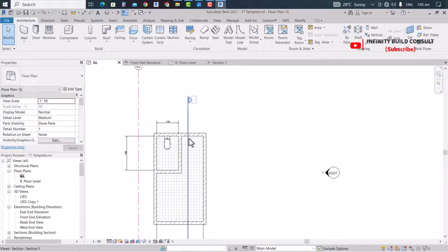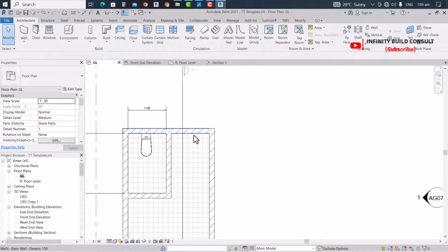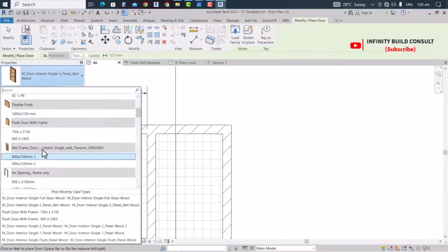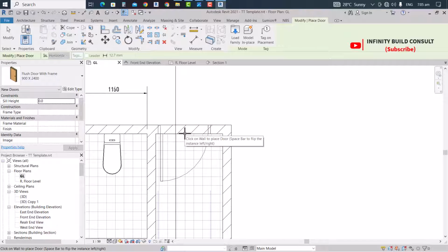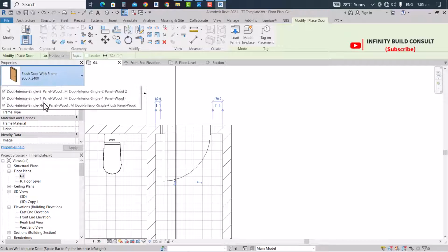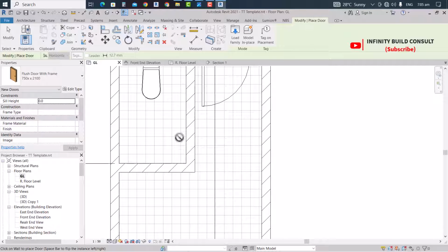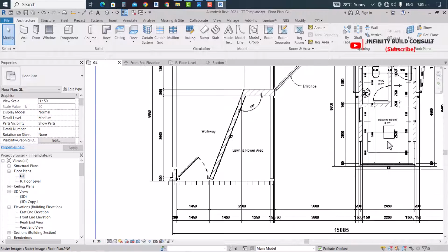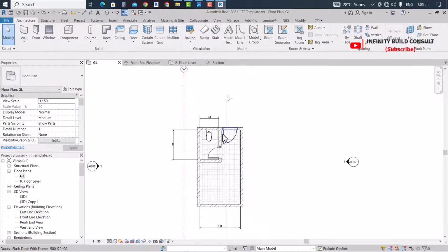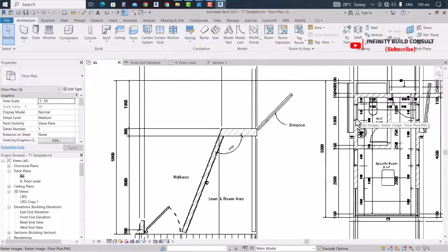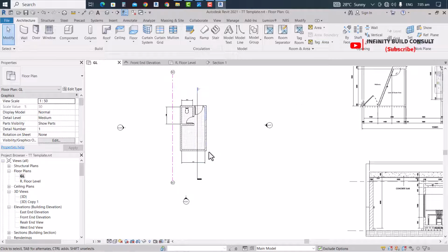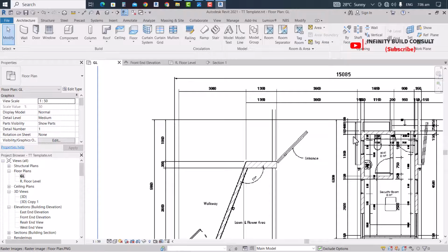Okay, the next thing that I'm going to do is to create a door, which has a shortcut, which is DR. Then I'm going to change the width of my washroom door to 750 by 2.1. So we are also going to make a reference to the distance here.